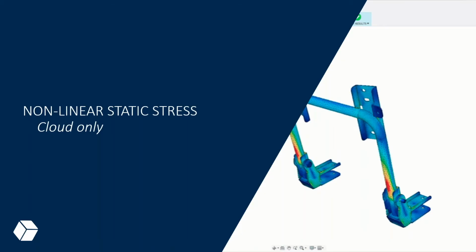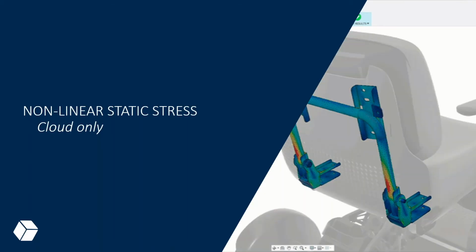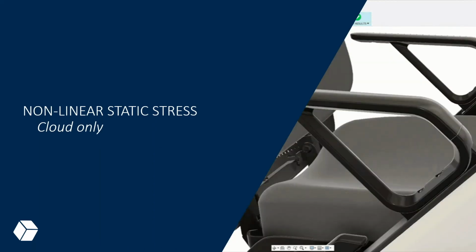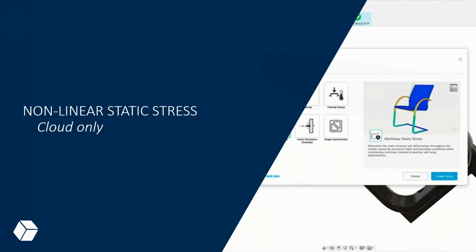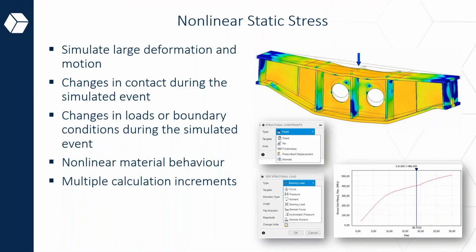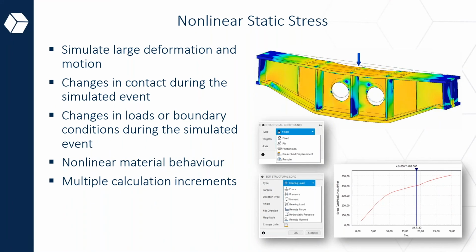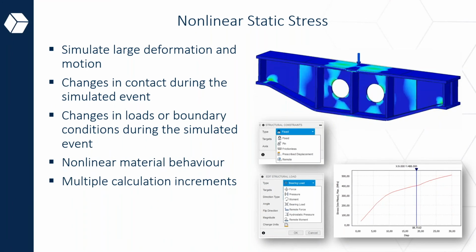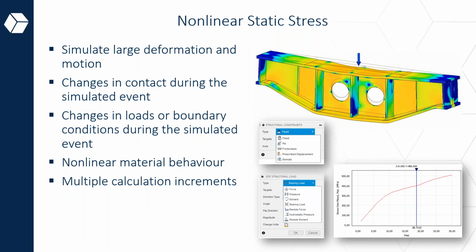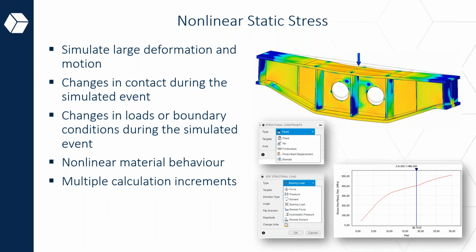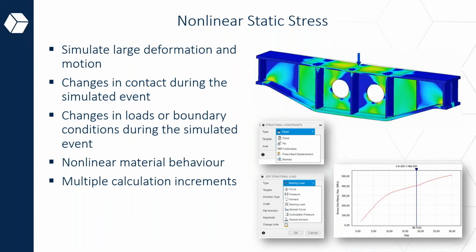Moving on to the next simulation mechanism that we've got, what we call non-linear static stresses. Now, the shape of your part and the way in which it deflects during its motion due to the force or the load being placed on it is simulated here in a non-linear fashion, because linearity is tiny minor deflections and it works on a single line.